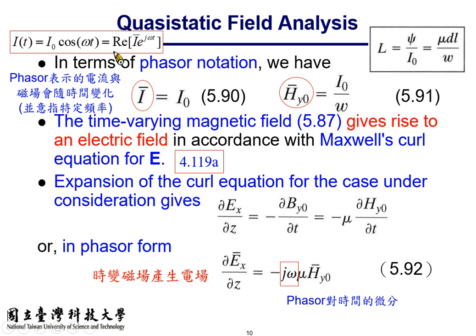And if you want to transform the phasor representation into the so-called instantaneous form, here the left hand side and the middle are the instantaneous representation of the current signal. It can be found from the phasor representation by multiplying the phasor with exponential j omega t and taking the real part of that.